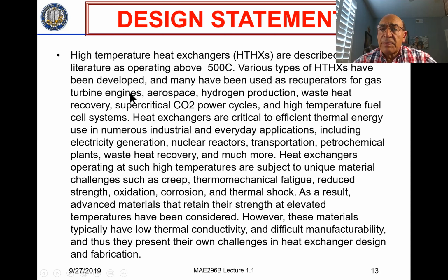heat exchangers for applications in turbine engines, aerospace, hydrogen production, and so on. So these kinds of applications require temperatures that are really high, above 800 degrees centigrade, for example. Not so many materials can work in that temperature range. Not only that, but they also require very high pressure, on the order of 80 bars. So 80 bars is like 8 megapascal pressure for one of the streams of the heat exchanger.